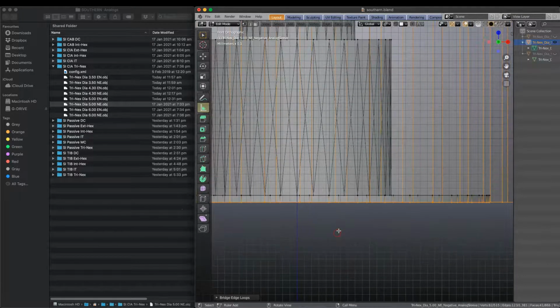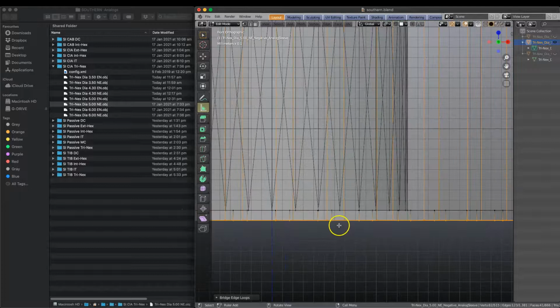Now we don't know which one of these edge loops lies higher up on the Z axis than the other, which means our cutting tool will not be able to select the correct surface. In order to make this a surface on the horizontal, we have to match these two edge loops.